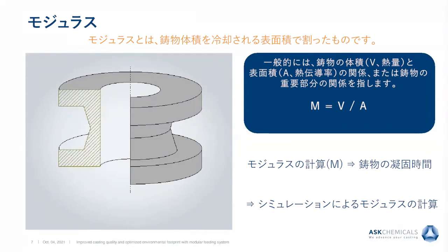In this case, the volume stands for the heat content of the section or of the casting, and the surface stands for the heat lead off of this section or casting. So even if we calculate geometrical values and have a length as a result, this length does not really stand for the geometric length. This stands for the time of solidification of castings. This is an important point.